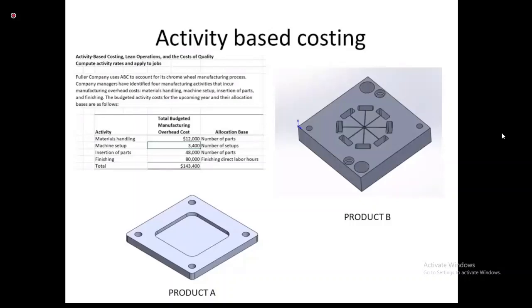And once you come to know what is the final product price, then you will start doing the optimization of the expenses for every activity. Now in most of the organizations, people don't work based on activity based costing. They will simply find out how much machining time is there on the component. So based on machining time, labor charge, and machining per hour rates, they will find out the cost of the product, which is altogether wrong.